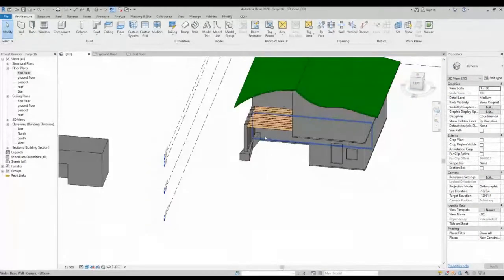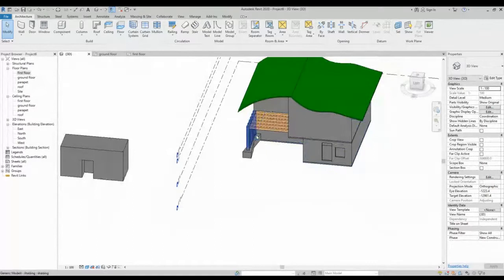Okay, so let's start with the mass modeling. Here we were working in the architectural tab and selecting components from here. But we have another tab, which is massing inside, which is to add things around the building or things that are supposed to be part of buildings and so on. So these are not like furniture or ducts or shading or any other thing.